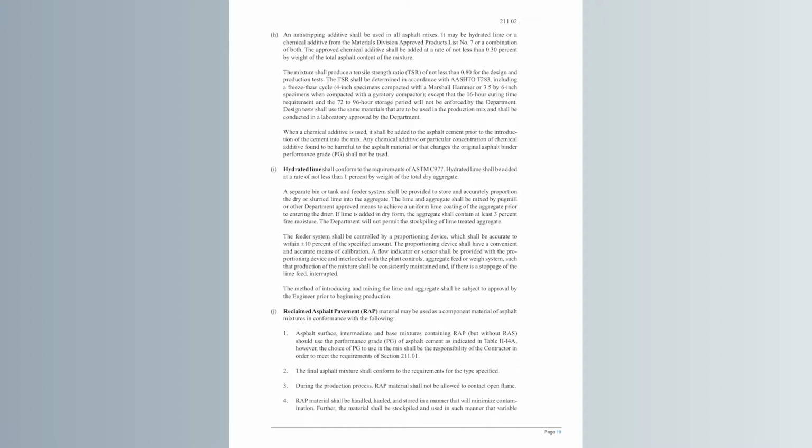And it needs to be added at a rate of no less than 0.3% of your total asphalt content of your mixture. Once you add your anti-strip additive, you also need to run TSR testing. Specification requirement is no less than 0.8 for your design.